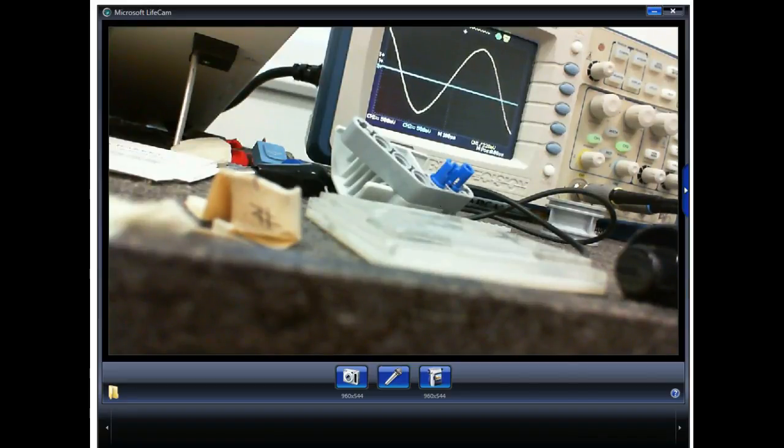Now this guy here is definitely bad. It's just up to us to try to figure out what it is. And this is one of them that's a little harder. And why is that? Because it looks pretty good, right? Whether it's saturated or whether it's in cutoff, the thing looks like it's in the active region. But there's no base current.